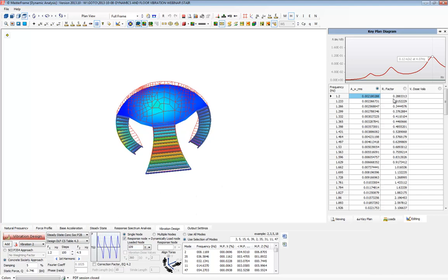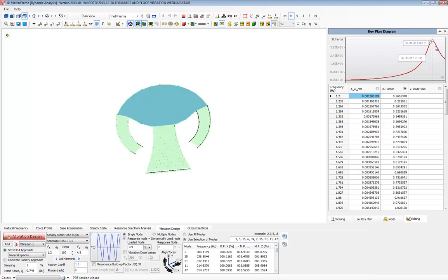And straight away we're getting our response factor graph here, and this is a very classical looking one. I think it's nice. We're seeing our little peaks, and these are happening at resonant frequencies, and then we get our one big response factor up here, 16.18 at 4.07. So that's a nicely shaped graph. If we look at this SCI approach, it's absent the peaks, and we get our one big response factor, 39.31. So I'm going to move back to PowerPoint now to compare these two and talk about why they're so different.